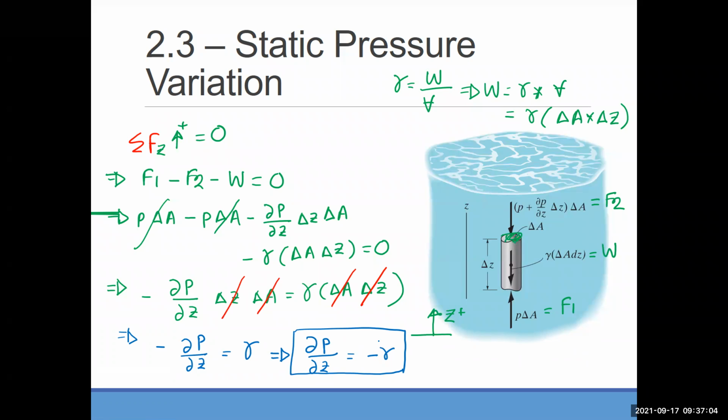Now just think about that. If you have 1 glass of water and 1 glass of molasses, I hope molasses specific weight is greater than the water. Yes. So which one will create more force on the surface? Molasses, because molasses individual weight or mass is higher than the water particles, right? If you have 10 feet of water and 5 feet of water, obviously the 10 feet will create more pressure on the surface, because it's more material. In easy words, the more material the fluid has, the more pressure it will create.